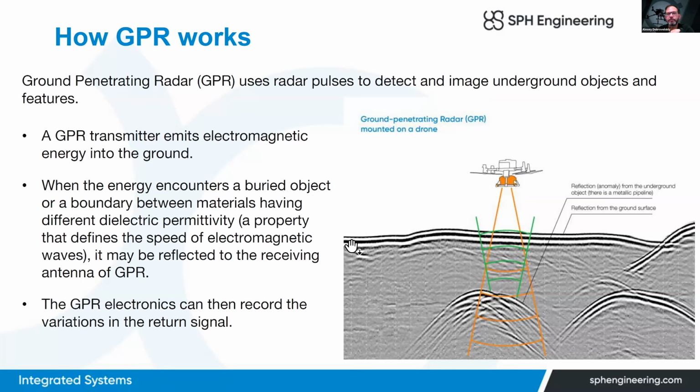First, we will see reflection from the surface. It is that strong line. If the antenna is elevated a little bit above the surface, usually we will see such a reflection, and also we may see layers like here, reflection from the different layers of soil, and also we may see something like hyperbolas here. In that particular case, hyperbolas are pipes crossed in perpendicular direction.